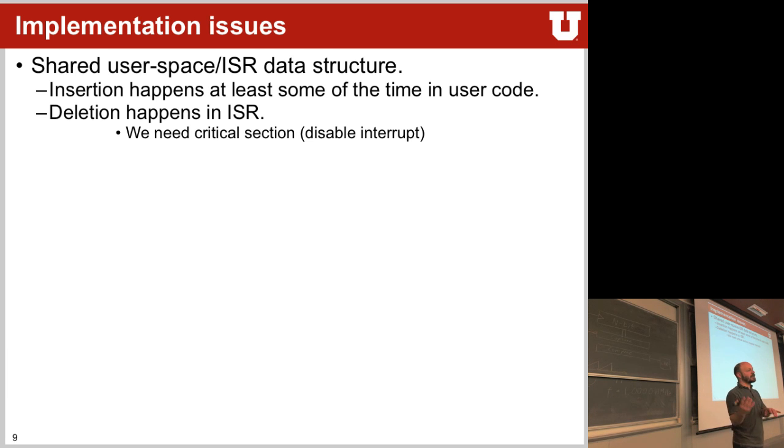So you have to be very careful and disable interrupts while modifying these shared variables and these shared components. Same with deletion, right? Deletion happens inside the interrupt service routine. So if you try to add something and then it comes and deletes something out of it, you can get a big mumble jumble with sharing these two elements.